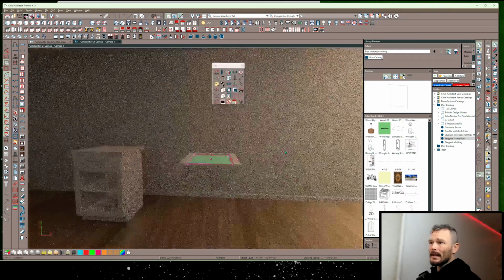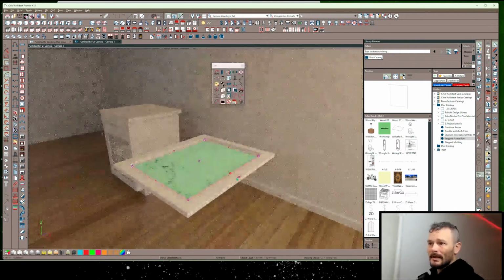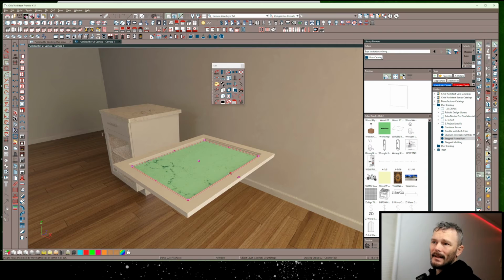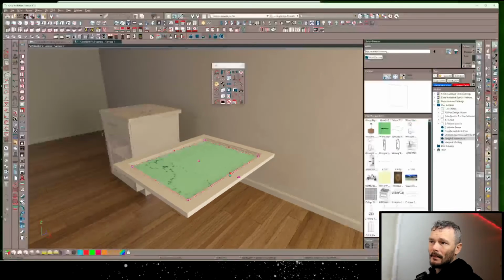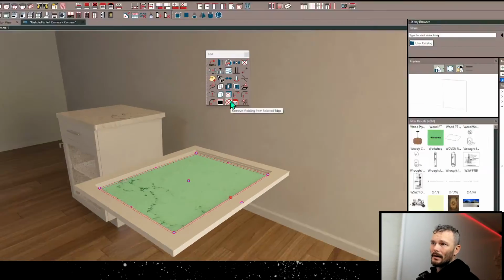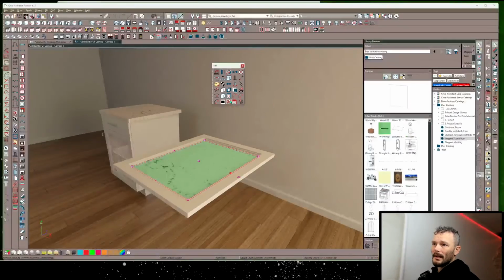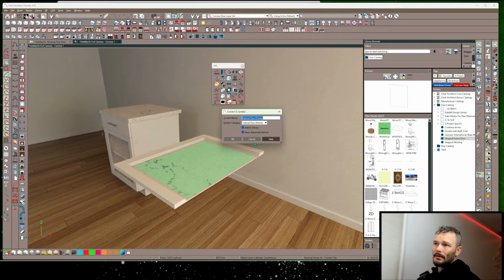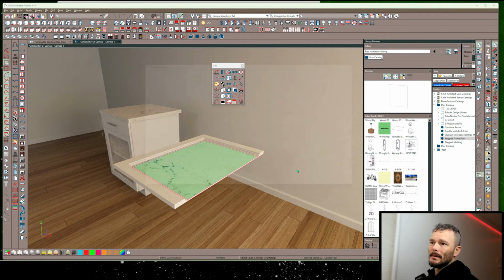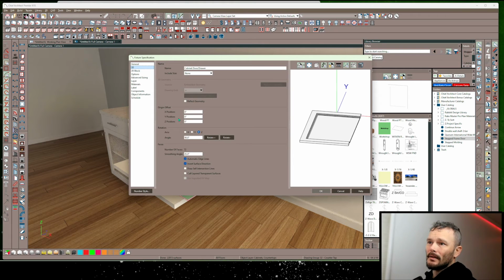Now let's get to the next part of this, which is creating the split frame. So on this selected edge, we know this is selected edge because we've got my highlighted color here, which is set in preferences. I'm going to say that I've got remove molding from selected edge. That's what it does. Bam. So now we can convert this to a new symbol. That's a cabinet door. Get back to that 3D panel.